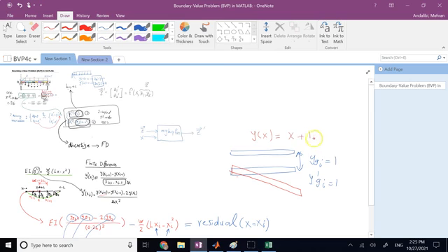The value everywhere is 1 except for the slope of 1, which is definitely not true because I know the two endpoints do not move. Right here at x of 0 you have 1 displacement, and at x of L, which is 3 here, you're going to have 4 units of displacement. So definitely that's a wrong guess.